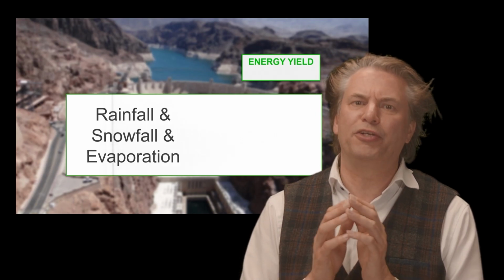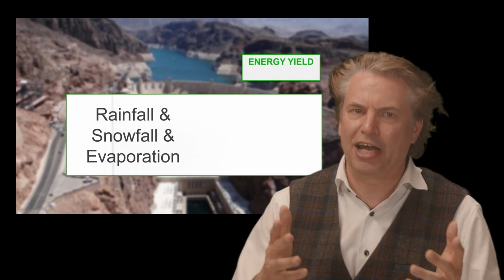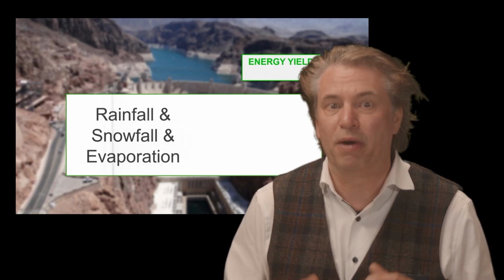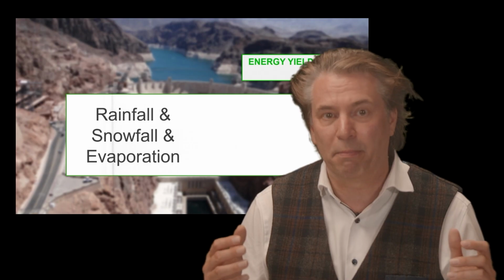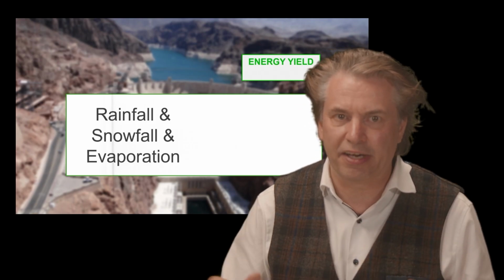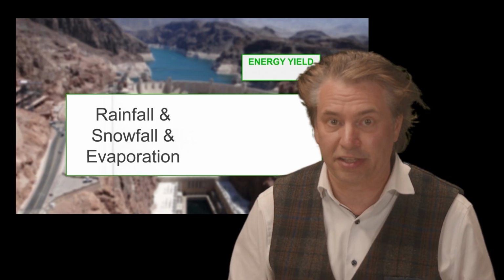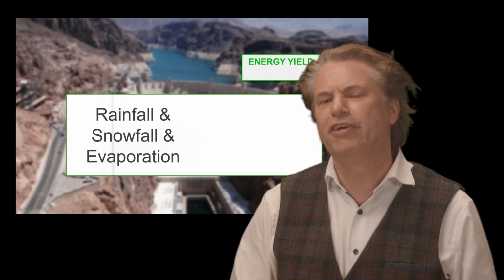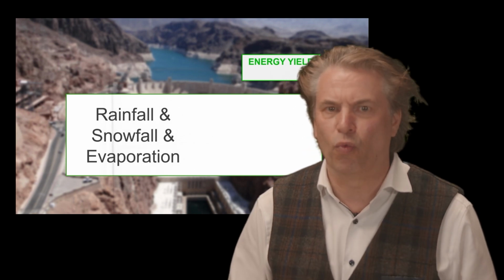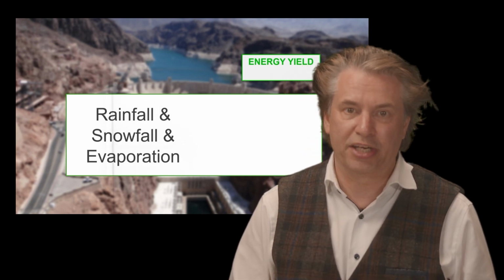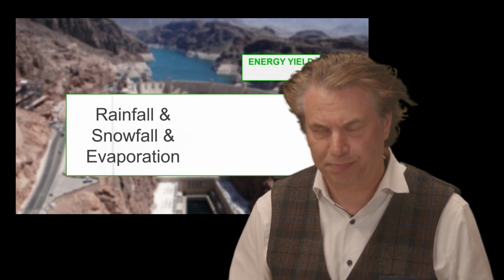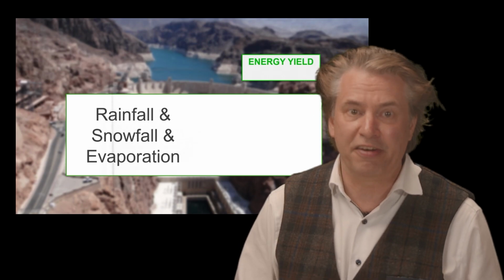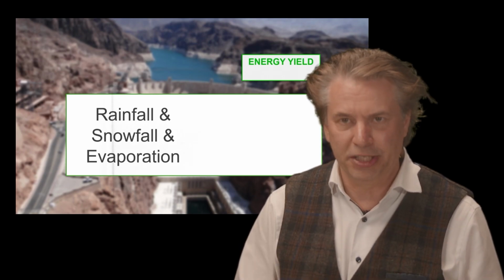The final annual energy yield, or the capacity factor of the hydropower plant, can be strongly influenced by the weather conditions, especially the amount of precipitation, snowpack melt, and the amount of water within the catchment area that is evaporated and absorbed by the vegetation before being utilized by the hydroelectricity dam. This affects the available water flow and the height difference of water, and consequently the potential energy that can be used. Therefore, the power output of a hydroelectricity plant can vary in time and even be seasonal dependent.